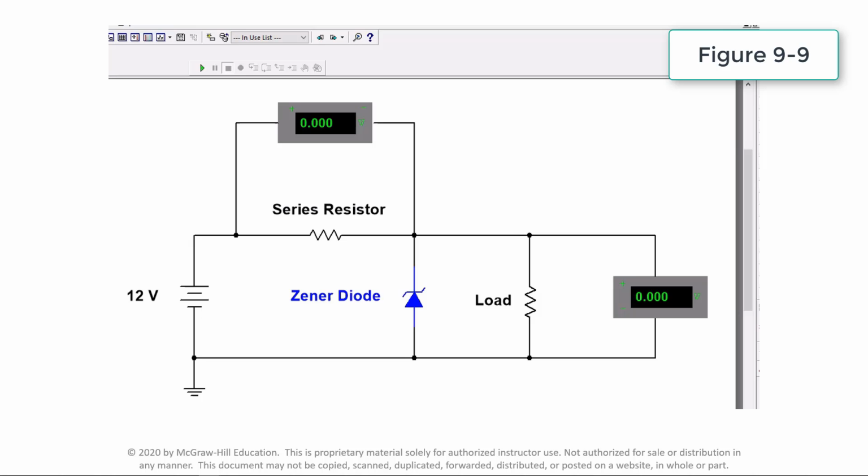A Zener diode is a type of diode that permits current to flow in the forward direction, like a standard diode, but also in the reverse direction if the voltage is larger than the breakdown voltage, known as the Zener voltage. They are commonly found as part of motor control feedback systems to provide a fixed level of reference voltage for the input and output devices.